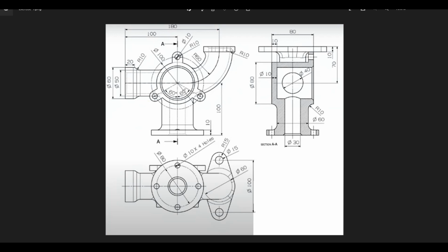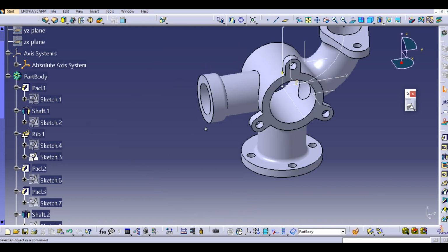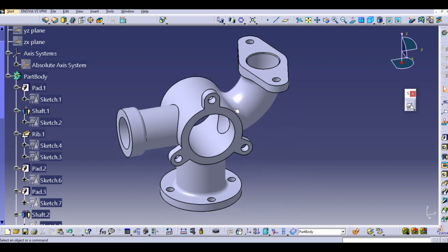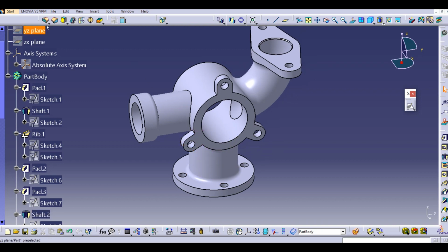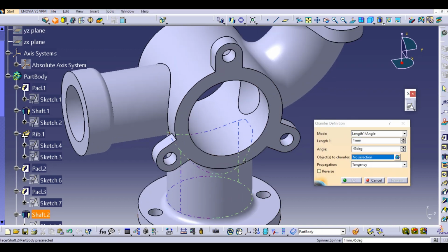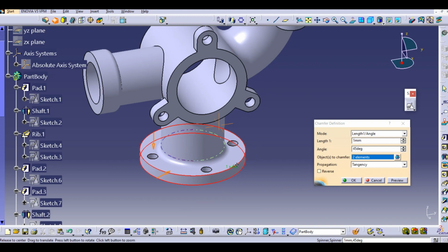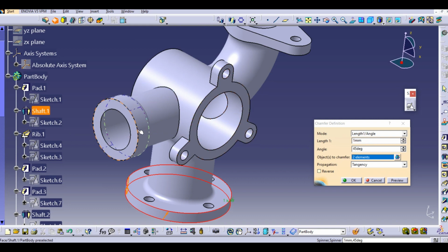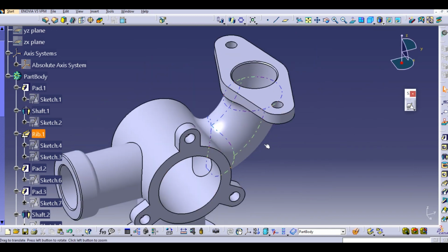Here you can see some chamfer available. So in this way you can create this model here, and you can just hide this unwanted sketches. Now you can also hide the axis system. So yeah, so this is we have created, and if you want you can add some additional chamfers here. Just add the chamfers for these edges. Let's add for this one as well. Just click on preview. You will see the chamfers have been applied to it.